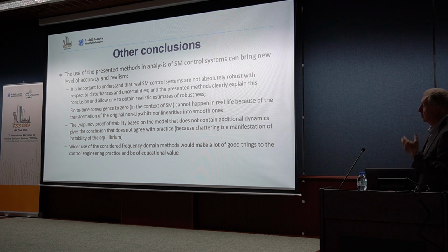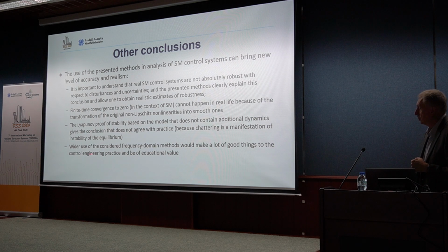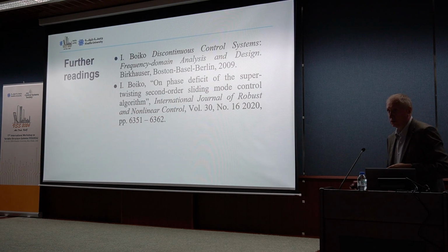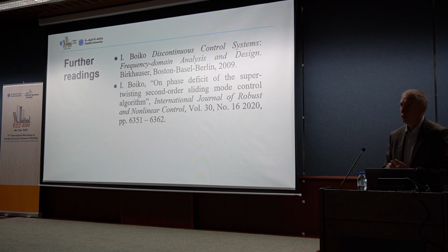Finite time convergence to zero in the context of sliding mode cannot happen in real life because of the transformation of original non-Lipschitz nonlinearities into smooth ones. The proof of stability based on models that don't contain additional dynamics gives a conclusion that does not agree with practice because of chattering, which is a manifestation of instability. And the use of the considered frequency domain methods would make a lot of good sense to control engineering practice and be of educational value. Some recommended references about the LPRS and the phase deficit.